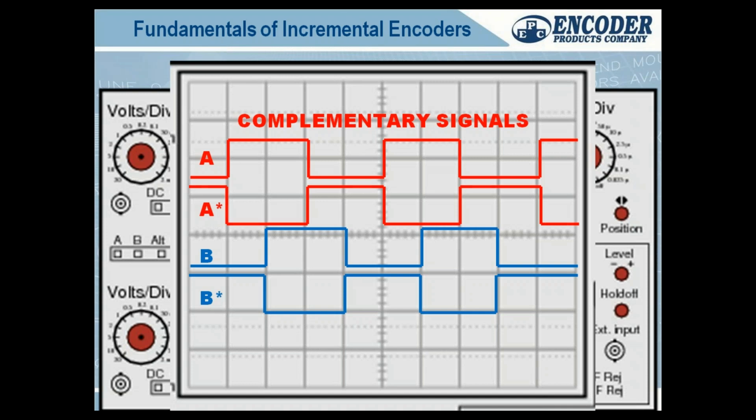So when I get into applications that are 24,000 RPM robo drills, for example, an incredibly high RPM on a spindle, you will see those encoders are bearingless, and they use low resolutions. They may be 256 or 512 or 1024 pulses per turn, so that when they're at 24,000 RPM, their circuit frequency doesn't exceed the 500K or 1 megahertz or whatever of the system. So as long as you can handle the frequency and you're not exceeding any kind of bearing RPM, fast as you want.